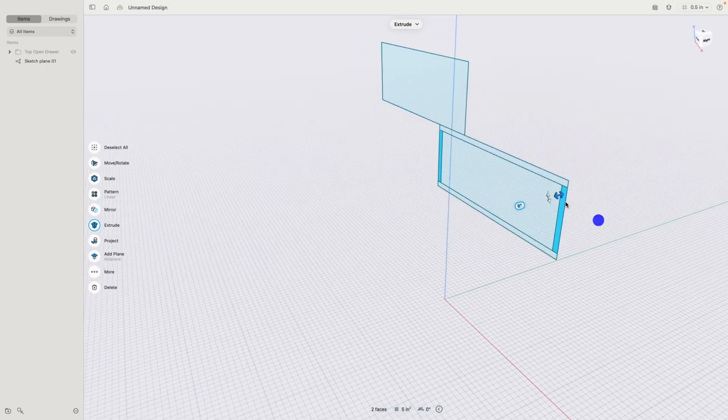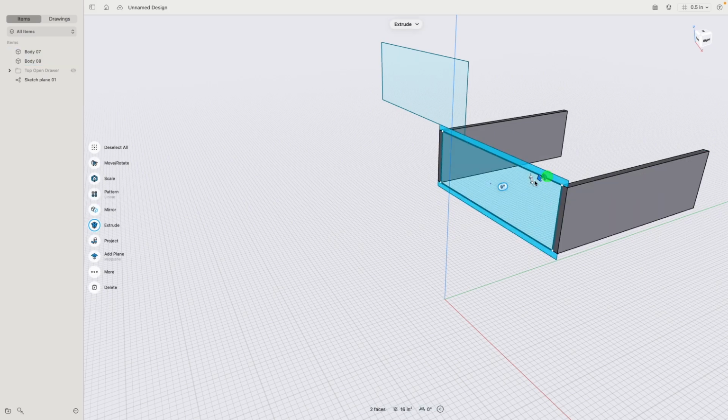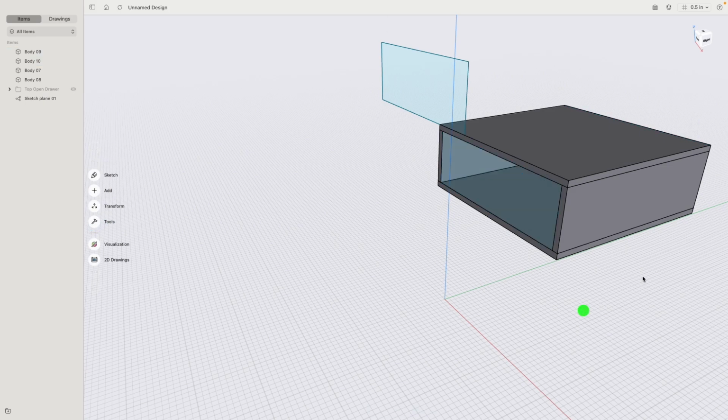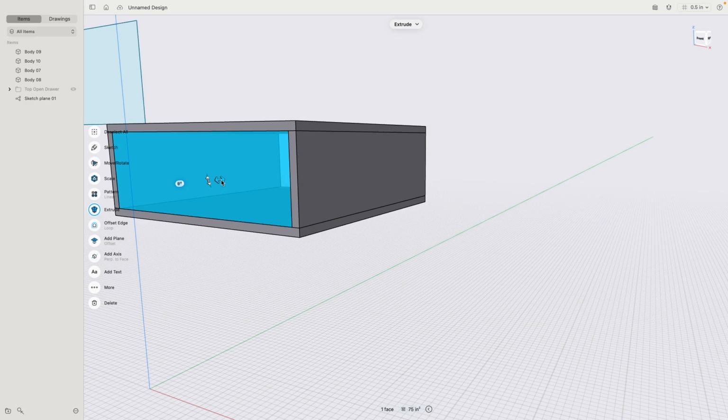So now what we can do is I will select tandem faces, there we are, and extrude them by -16. Then I can select these 2 and extrude them by -16. Perfect. The front we will extrude by 0.5. That's actually the material thickness.